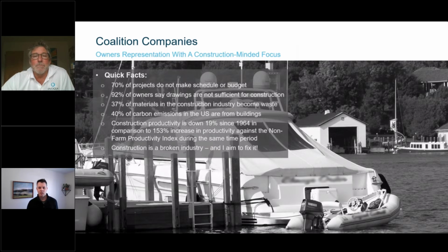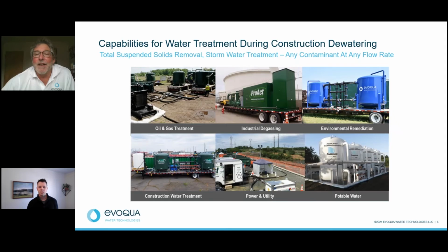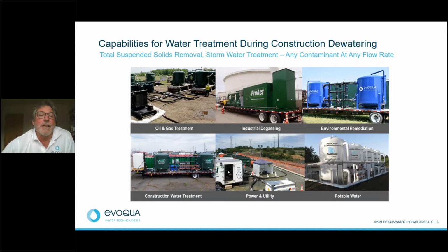So first, where do you typically need water treatment in a construction dewatering site? I think probably most of you will agree that foundation work is probably the number one thing. You're opening up a hole, you've got to dewater to get the foundation in, or an elevator shaft. That water's got to go someplace, and it usually has to be treated at least to get the solids out before you dump it someplace.